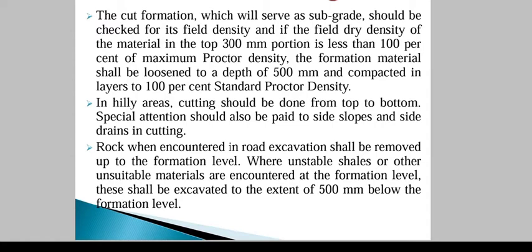If you are going for ODRs, other district roads, or state highways or MDRs, then instead of tunnels we'll climb up to a certain height of the hill, then we'll provide a small portion of cuttings on both sides to the required width of two lane. For example, up to 9 to 10 meters of width, or 15 meters of width of cutting is done, and we'll be providing the road, right.